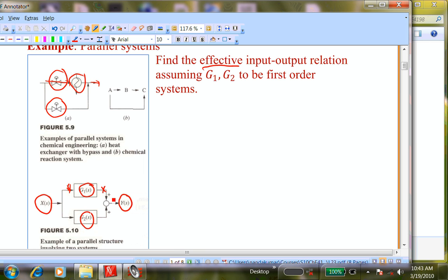Would you put a valve, like a control valve? Typically, when you have a bypass valve, one of them will have a control action on this. The other one is basically to regulate total flow from one range to another range. If you want to operate on high flow rate regime, for example, you shut this off completely and let all the liquid flow through that.